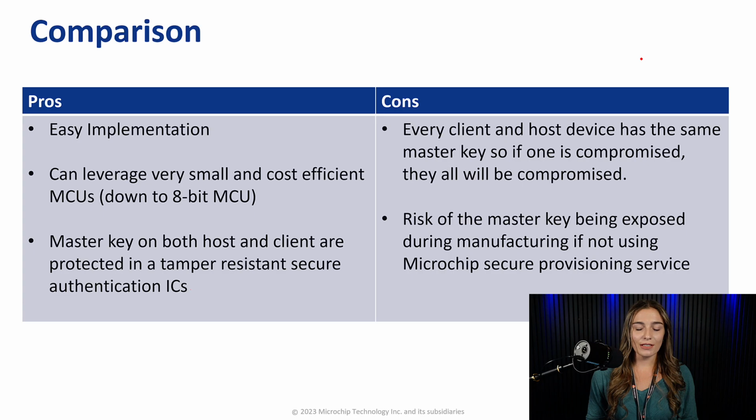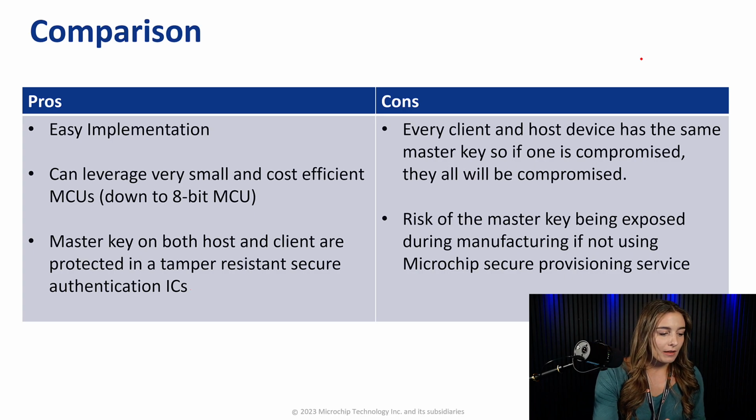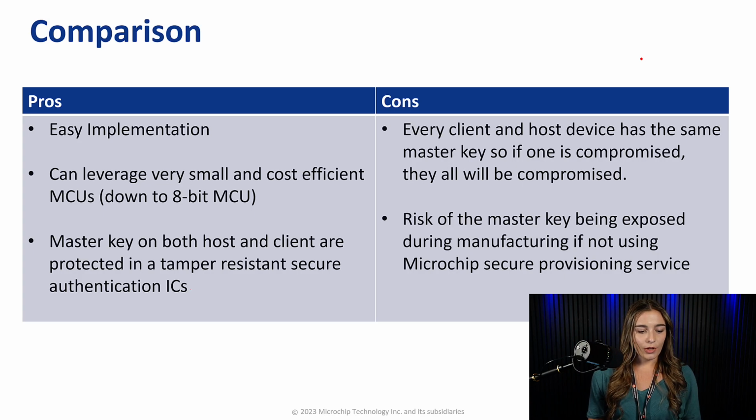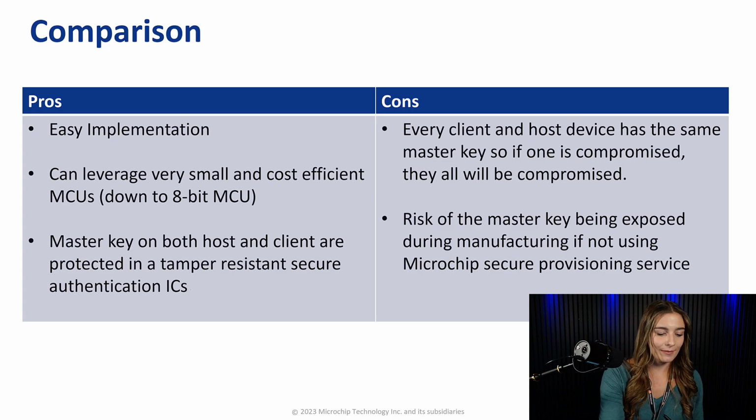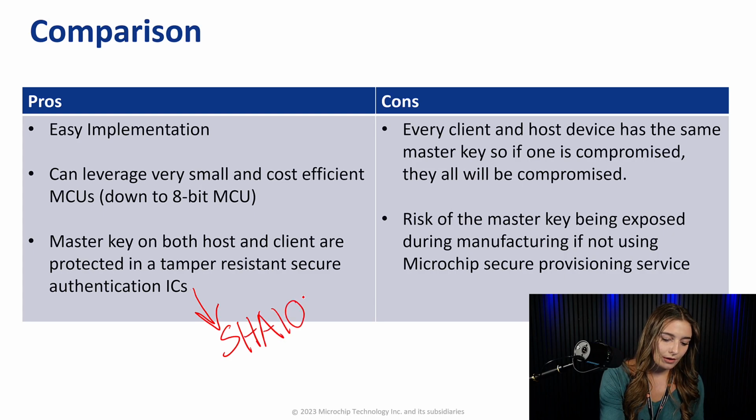Some of the advantages of Shared Key Symmetric Authentication is that it is very easy to implement. All you need is to put the same master key into both the client and host device. You can also leverage very small and cost-efficient MCUs, down to the 8-bit MCU, which can allow for easy integration into your already existing designs, or if you have any constraints on a project, it can help with that. The last pro we have here is that the master key on both the host and client device are going to be protected in a tamper-resistant secure authentication IC. And this would be our SHA devices, such as the SHA104, the SHA105, and the SHA106.